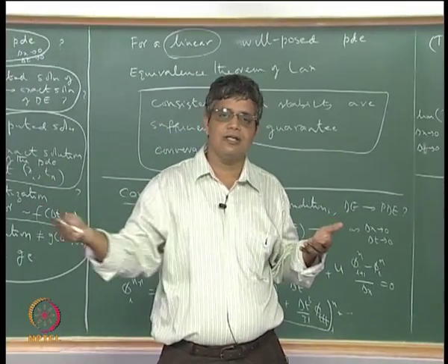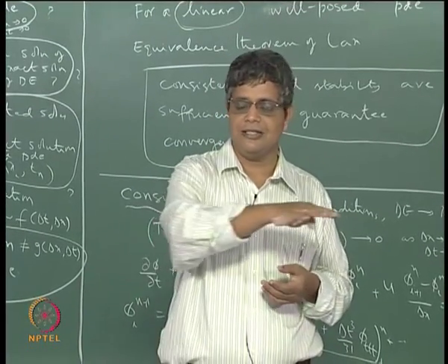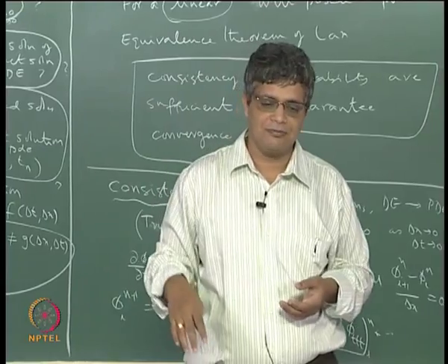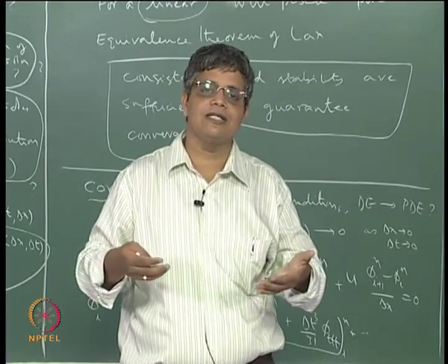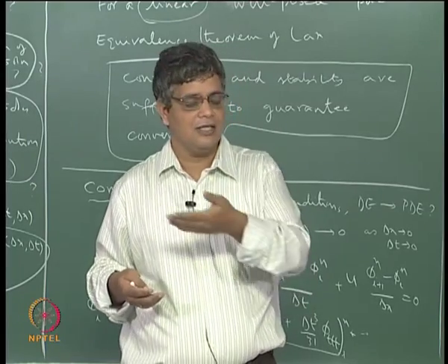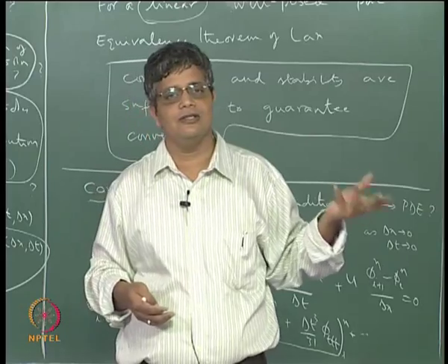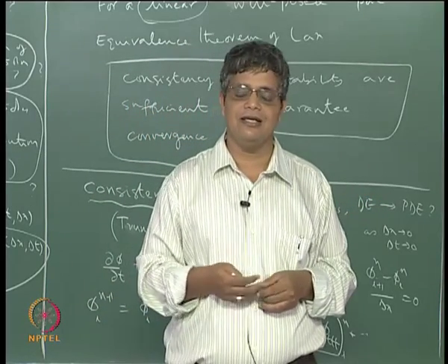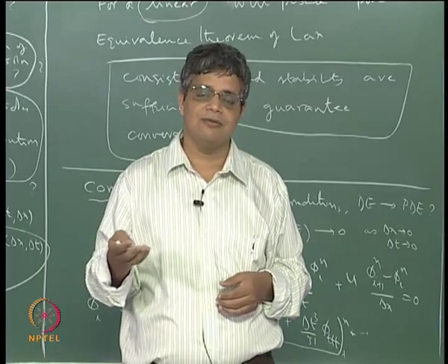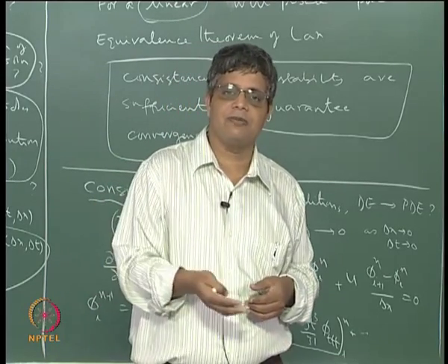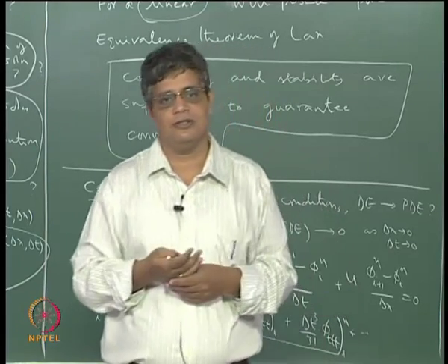you have an infinitely long plate, thin plate, which is submerged in this fluid and it is horizontal at a particular depth, and at time equal to 0 you suddenly set this infinitely long wide thin plate into motion in the horizontal direction, that is in its length direction, at a uniform velocity of a capital U. Okay, so because the fluid that we are considering is a real fluid with real viscosity, and because of the no slip condition, the fluid which is adjacent to the plate will start moving.